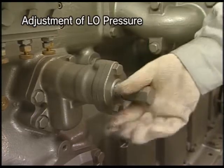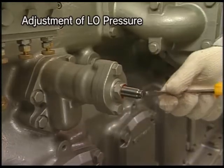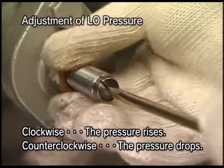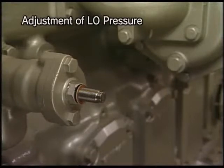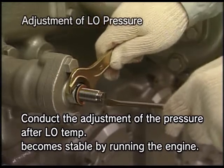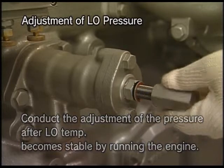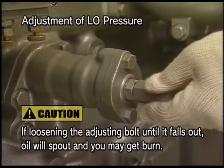Remove the cap nut and loosen the lock nut. Make adjustments by screwing the adjusting bolt and adjust the pressure. After the adjustments, securely tighten the lock nut, screw the cap nut, and the work will be completed.